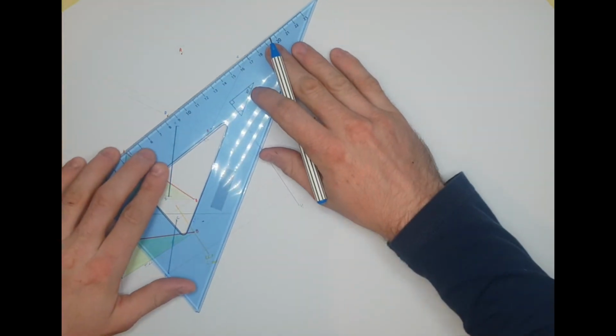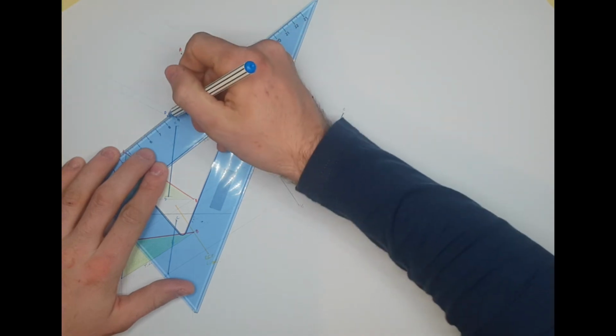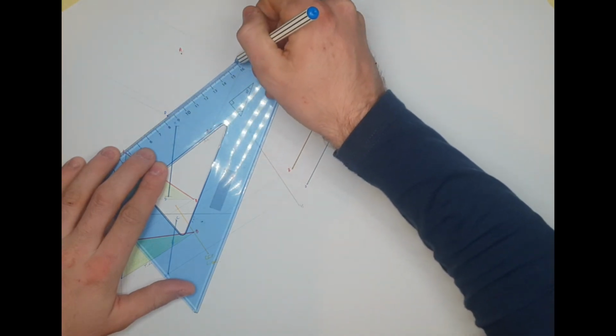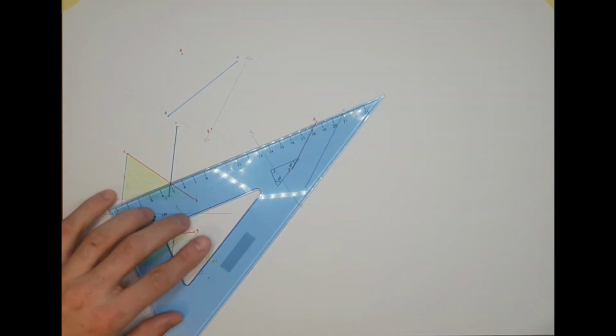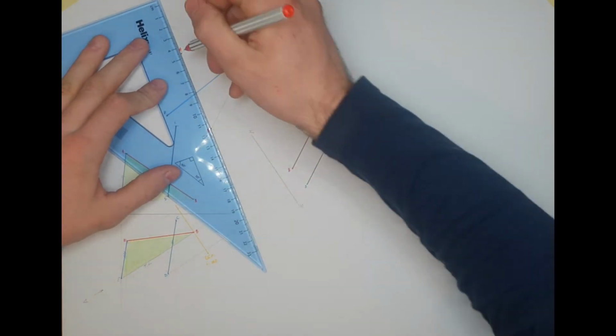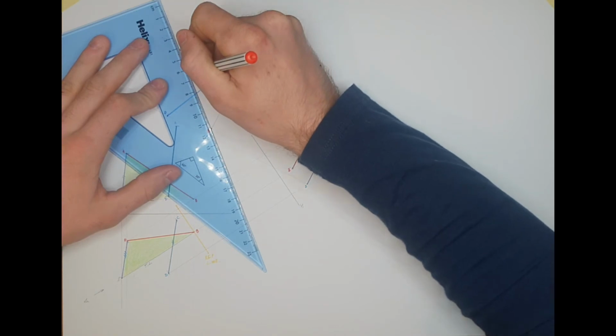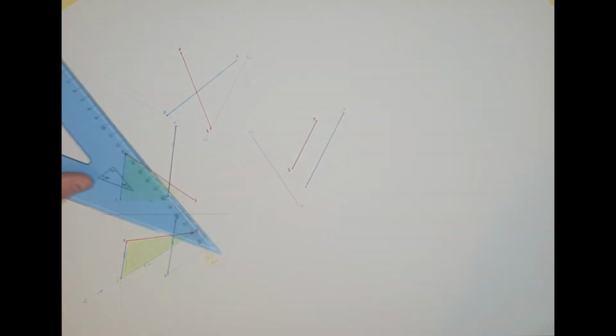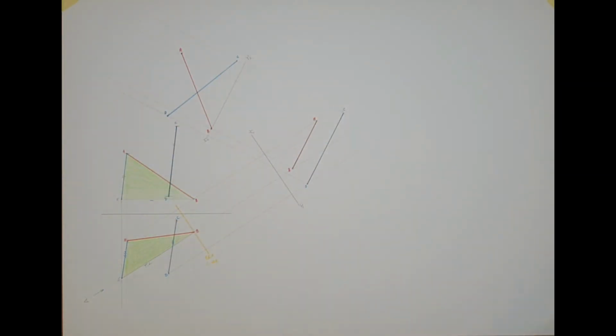Point C and point D define that blue line in this position. Point A and point B define this red line in this second auxiliary view. And where those 2 appear to cross gives me the shortest distance. Now I'd like to add a little note, and I'm going to add a lot of notes in here and maybe colour at the end of this.